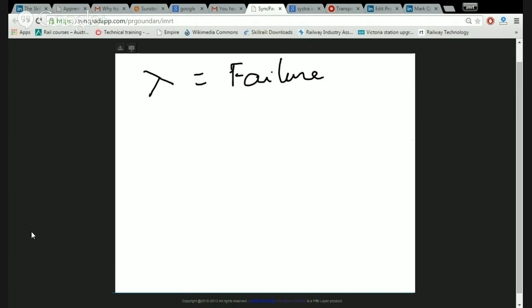If I make the equipment, run it, and conduct a failure test, I will find, okay, this capacitor fails so many times in so much time, so I get the failure rate. But now I'm designing, I don't know anything. So how do I do this? How do I get it? So basically, it is prediction for each component which is in the PCB. Methods.